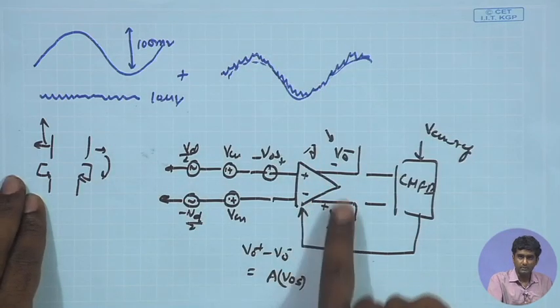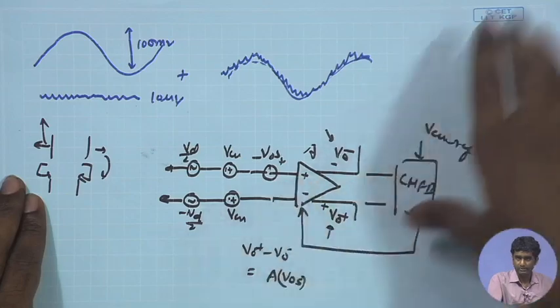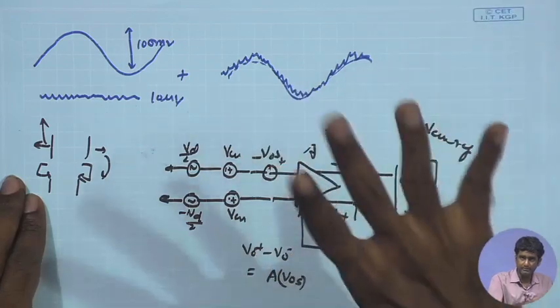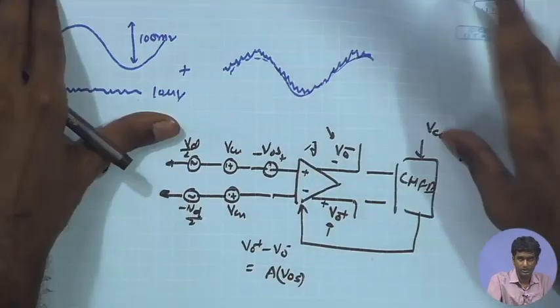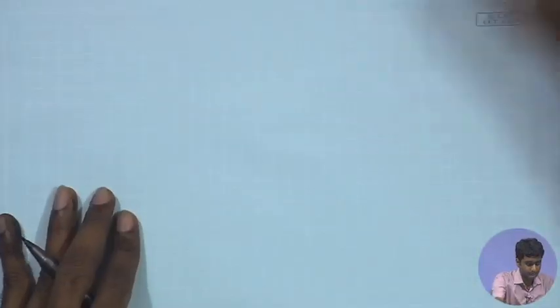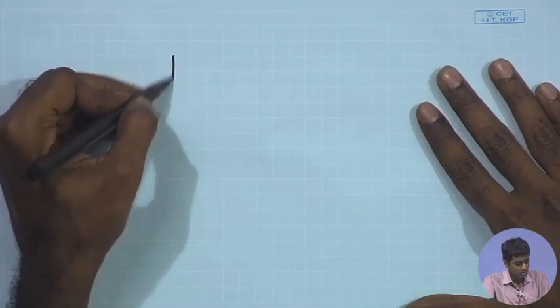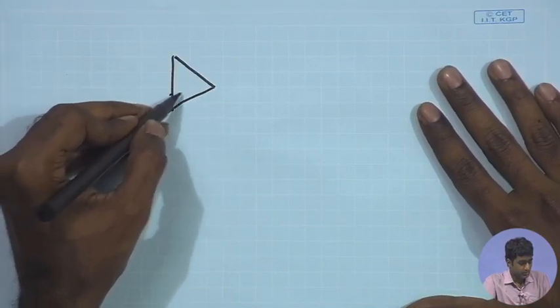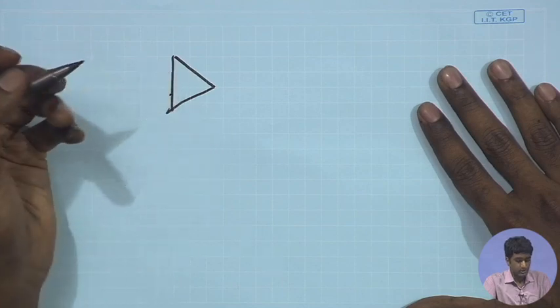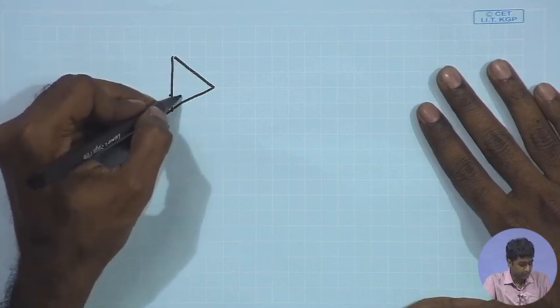As a result, the resistive feedback that we have for the biasing, we can see that that itself can help us in mitigating the effect of offset to good extent. Let us see how does that help us. So, let us look at the single-ended version.